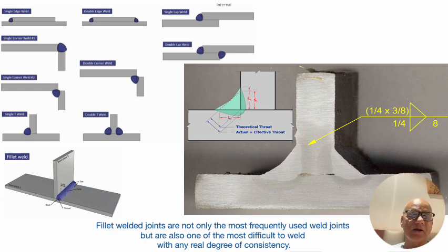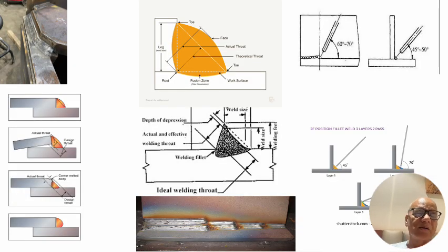So I will move to the next slide now. As we were discussing, one of the angles, in the direction in which we are welding, the angle of the electrode is required to be maintained as suggested here, 60 to 70 degrees. For most of the processes we maintain this 60 to 70 degrees in the direction in which we are going to continue. But in the other direction, the cross section, we have to be as perfect as possible depending upon the position where we are putting the fillet.